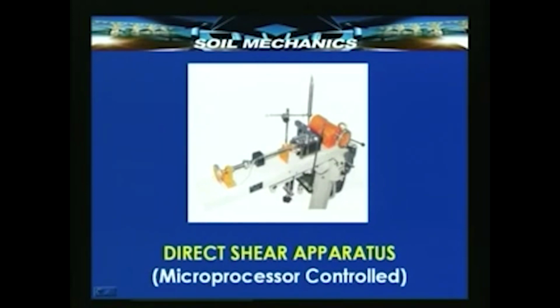It is also a strain control device, but it is digital. It gives you all digital displays. It gives you 100% control over application of loads, both normal and tangential. So, this is the latest modern version of the direct shear apparatus, also strain controlled.